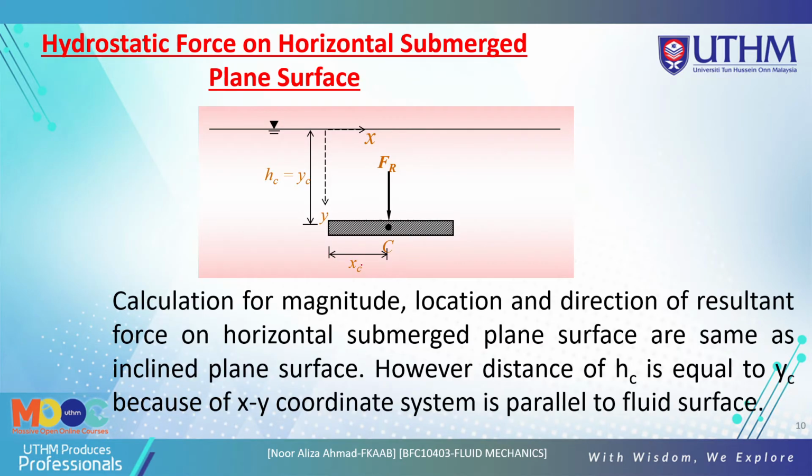Now we look at the hydrostatic force on a horizontal submerged plane surface. The previous slide was inclined. Now we look at the horizontal submerged plane surface here. This plane surface is horizontal and submerged in the fluid. So we have YC equal to HC because this is horizontal.